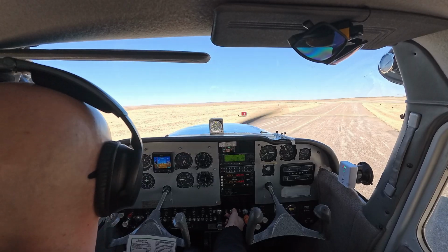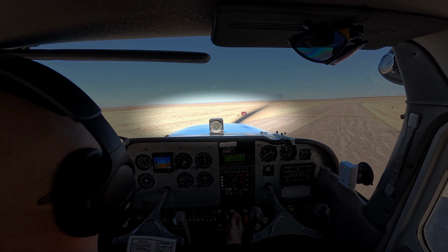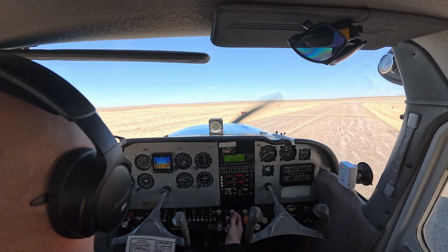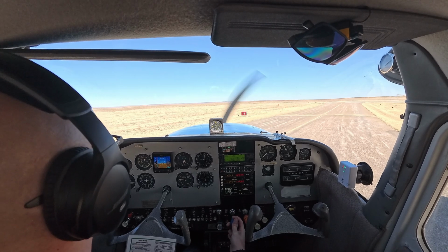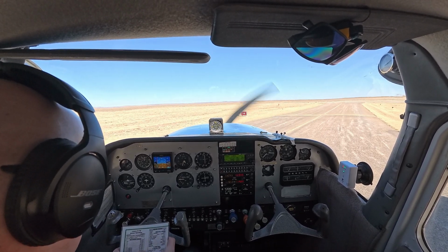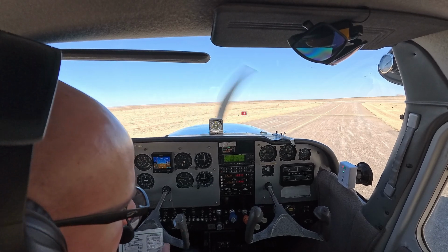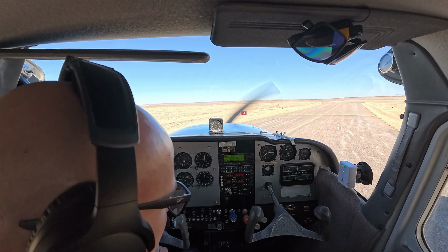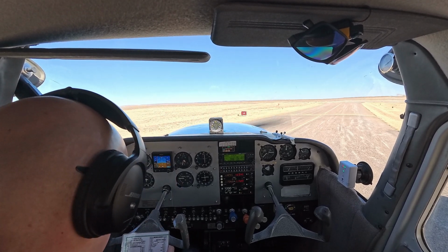On the third pull, you're going to be looking at the propeller hub area in the cowl. During the cycling of the propeller, this is the first time you are sending oil to the prop hub for the flight. This is the time to look for any leaks that could be coming out of your propeller hub. So on the third pull, pull the propeller knob all the way out, verify there's no oil spitting out from the propeller hub, and then push the propeller lever back in. Upon completion of your 3 cycles, you have verified that the propeller governor is operating as it should and that there are no leaks in the propeller hub.